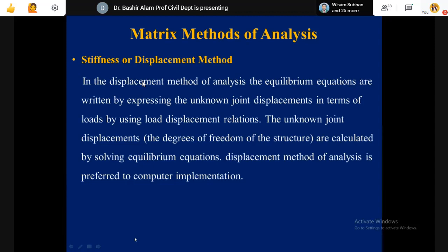Now, how will you prevent the rotation? When you clamp this, how do we clamp it? We provide just a fixed support there. Okay, you have made this kinematically determinate by stopping the rotation. Theta is now zero, but what happens when you clamp this and you are not allowing the rotation? The moment will be generated there now, which is not there in the original structure.